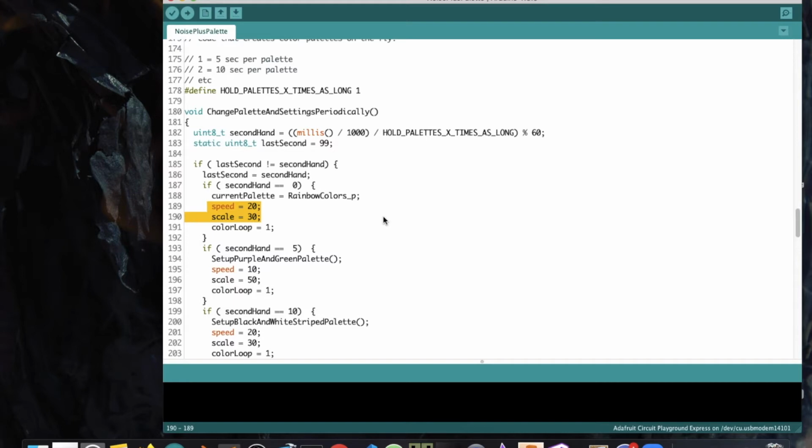You can use it to get a convincing 2D fire, water, or clouds effect, especially if you turn the speed down and just let the noise slowly evolve over time. It's not just for matrices either, since it also looks cool on the one-dimensional array of a strip. There is a 1D version of the noise function you can use for this. Simply call inoise8 with x instead of inoise8 with x, y, z.